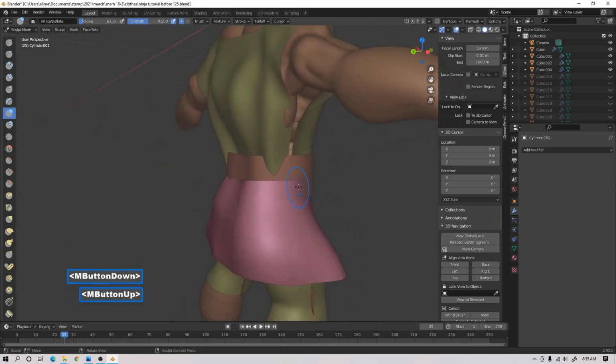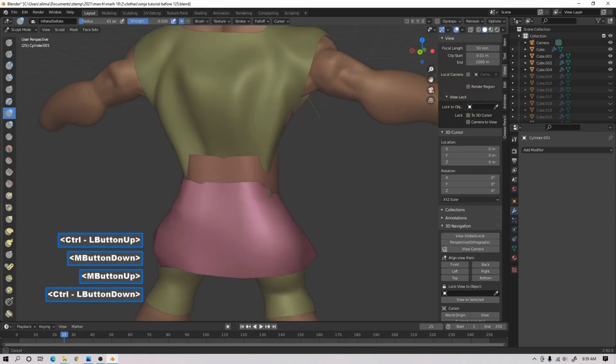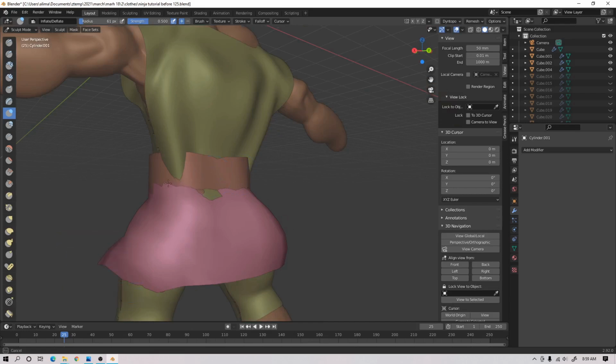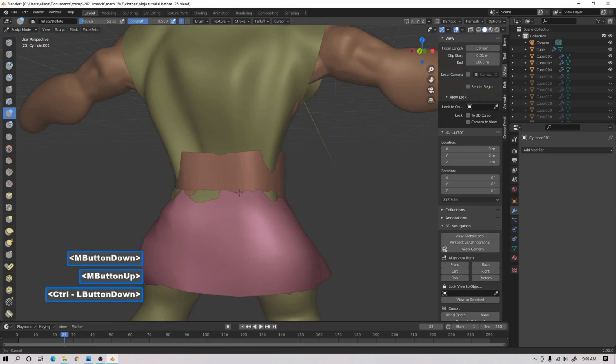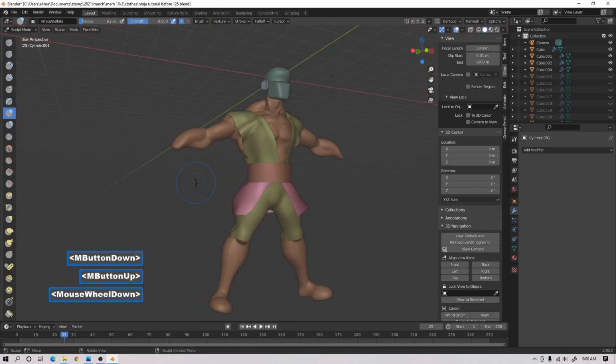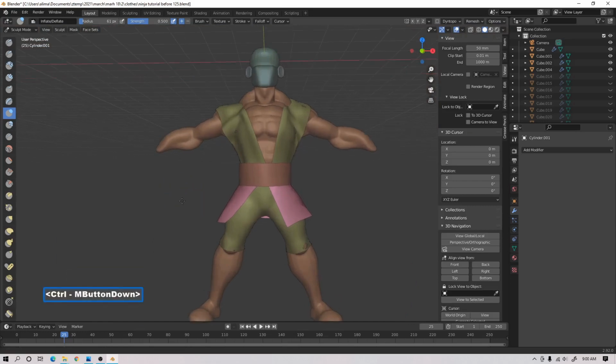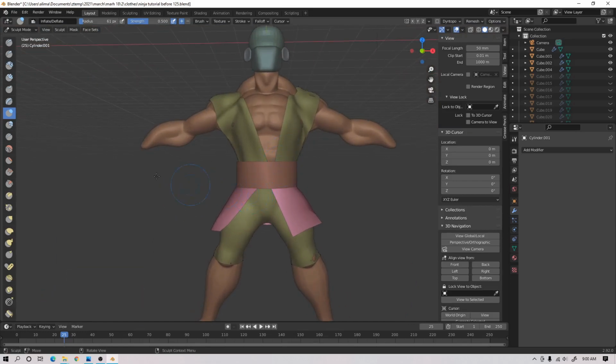In Blender. For this here, we can use the opposite. I'm holding Control. The Control does the opposite. So most tools in Blender you'll find make things come out, with the exception of things like the crease brush that you will tend to use a lot. When you hold Control, things go in. So I want this part to come over here more.